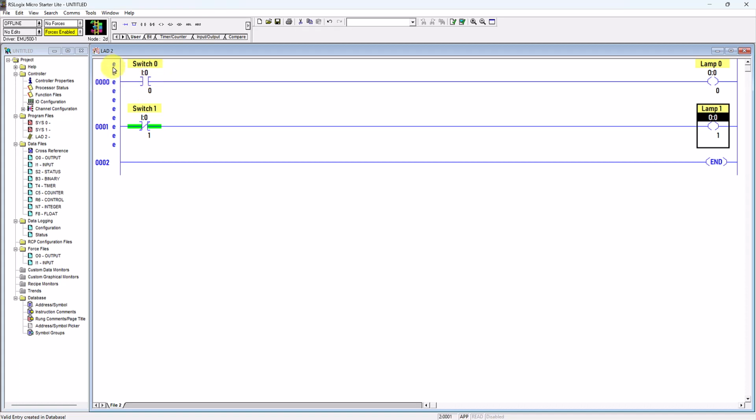Then the virtual power will flow through here to energize the virtual output coil. So this will cause the digital output internal normally open switch to trigger to close, and then the current can flow through this digital output circuit and activate the external load such as lighting, buzzer, contactor or relay, etc.